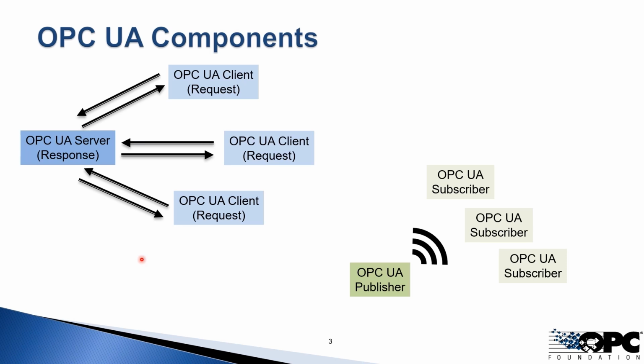The required behavior implied by the OPC UA specification largely centers around the interactions between these components, and hence OPC UA can be considered a decentralized architecture that doesn't rely on any centralized components. So this decentralized concept allows very small OPC UA systems to work easily without any burden of centralized components.